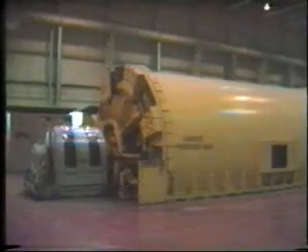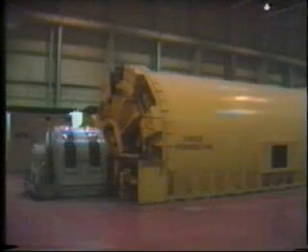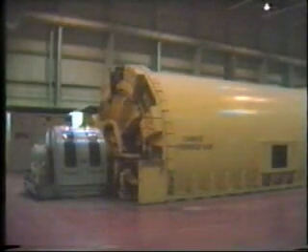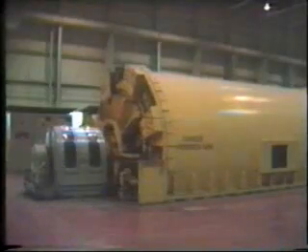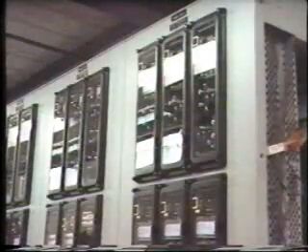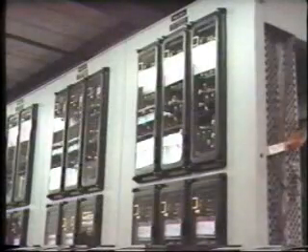In practice, it is probable that the generator automatic controls may attempt to increase generator internal voltage in order to compensate for some of the voltage drop downstream. However, this would take some seconds and therefore should not interfere with the operation of protection relays, nor with our studies of fault characteristics. Let's take our study a step further now and consider the magnitude and phase angle of the various impedances.